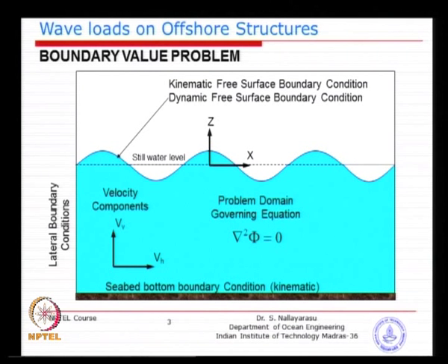So, what you just need to solve is a domain, basically this 2-dimensional domain described by fluid flow. I think this is what you are going through just now, using basic continuum mechanics from continuity of mass and various conditions applied. You can derive a Laplace equation to describe the fluid domain, and then apply boundary conditions at the surface, at the bottom seabed, and at both ends. So, taking a finite domain like this, you could solve the problem using various mathematical principles.